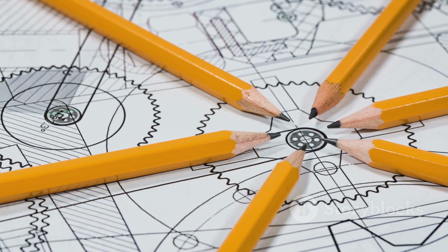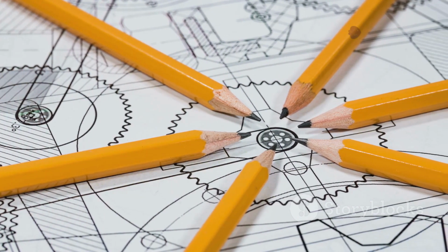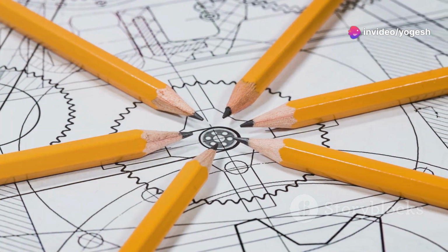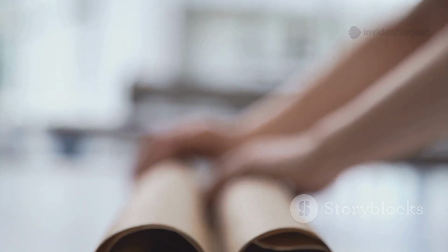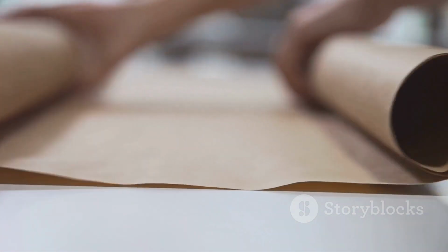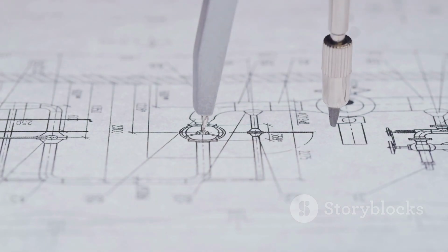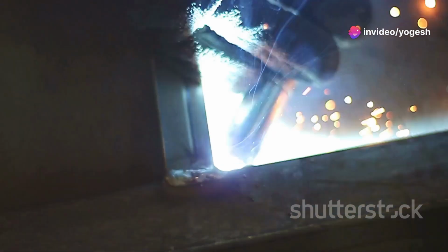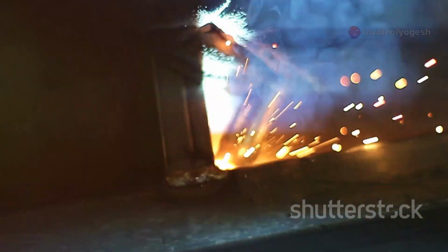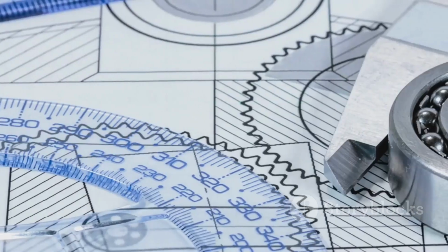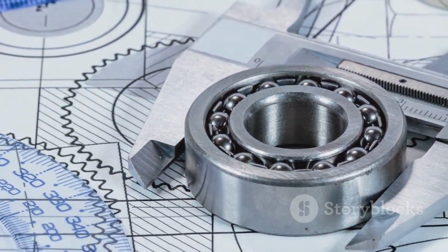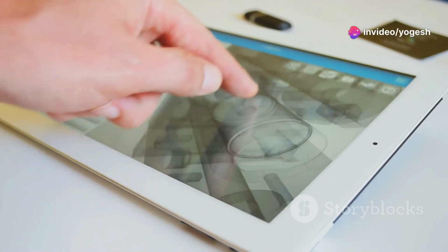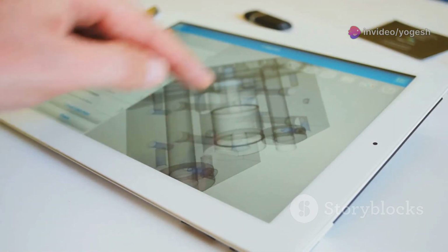Always use established standards like ASME, ISO, or DIN for things like surface finish, welds, and especially for geometric dimensioning and tolerancing, or GD&T. These standards are recognized globally. A proper weld symbol or surface finish callout can pack a huge amount of information into a tiny graphic, saving space and making your intent crystal clear to anyone reading the drawing. GD&T symbols control the form, orientation, and location of features far better than written notes ever could. They remove ambiguity and ensure everyone is on the same page.